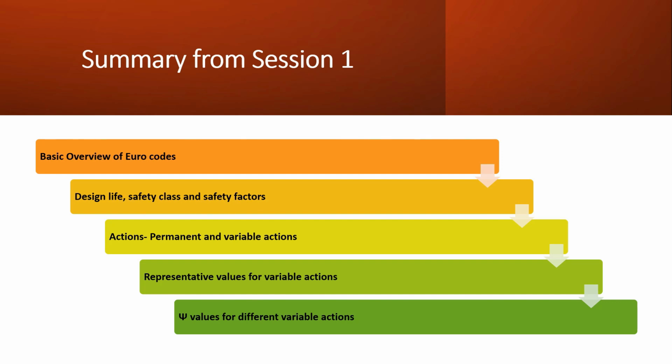I gave the basic overview about the Eurocodes, then design life, safety class and safety factors, then actions, permanent and variable actions, the representative values of variable actions, and psi values of the different variable actions. Why am I asking you to watch my last video? Because I will use all these things in making the load combination. So if these terms are not clear to you, the load combination concept will not be clear to you.